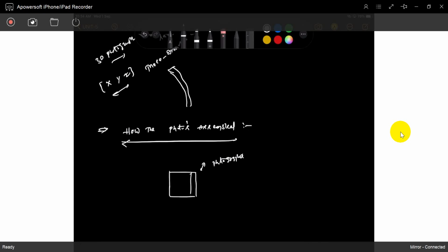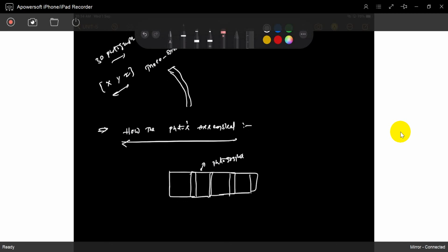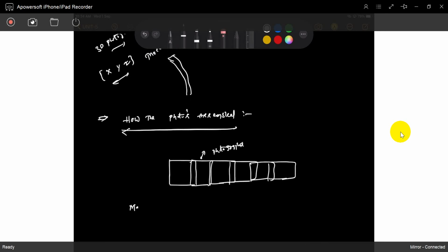If you assemble every photograph in a very simple manner, there is no need to take any reference points. You can just assemble it, and you see this is like a map of that area. There are no control points. Just by visualizing, you can attach them like this. It is called a mosaic. You just take the photographs and place them on your table, very normal, with no control points. You get some map, and that map is called a mosaic.